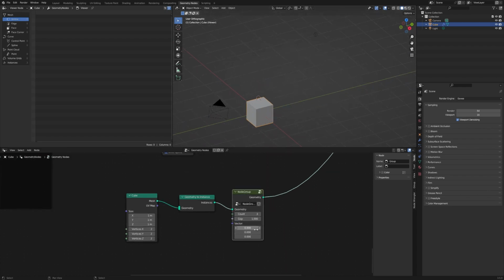If it's, as an example, do 1, and let's send this in the y-axis, and there we go. So what that's now doing is it's multiplying this number by this 3-dimensional vertex. So if I make that gap 2, there, I mean, you can in theory do 2 here or make that 4, but the best way of using this is just this defines your direction, this defines your gap, and then your count will just be the actual number of times that you're using that.